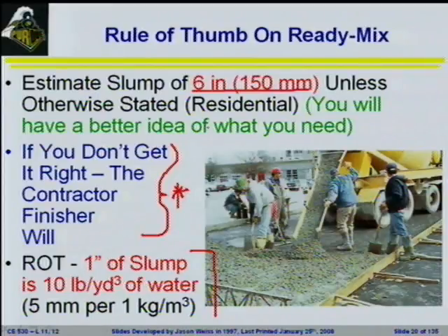I don't think that's the best way to design concretes, because you have much better controls at the plant, and everything's on the batch tickets. There's less confusion. So I think there are ways to design it properly, and I will get to that when we talk about quality control and field concreting issues, I promise. But in general, unless you're very aware of all those criteria, don't add water. That's the general rule. There are a few exceptions, but a lot of the time people just want to add it for no apparent reason other than it makes it easier to work.